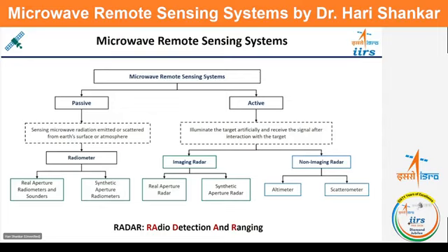So hydrology studies you can do using the altimeters also. And if you have a very precise DEM also, then you can calculate the depth of the water also. So that is called bathymetry. So bathymetry applications can be done easily with the help of the altimeter data sets.